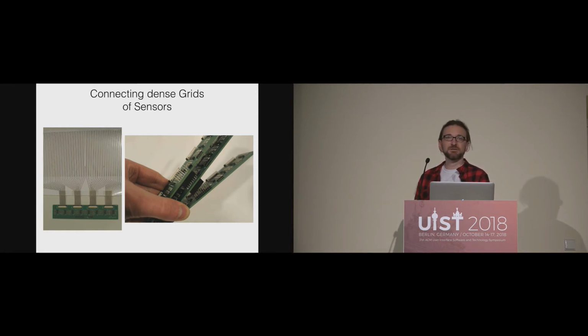And for this, we developed a ShapeMe board. It contains FPC connectors, and it's a plug-and-play system. You can just put these connectors in and click, and then it is connected. And this enables makers to also connect larger and high-resolution shape sensing sheets. In the example that we saw before about these volumetric objects, shape-aware material can also have multiple layers. And for this, we made the ShapeMe board also stackable, so you can even connect more of these boards together to sense even more sensors.